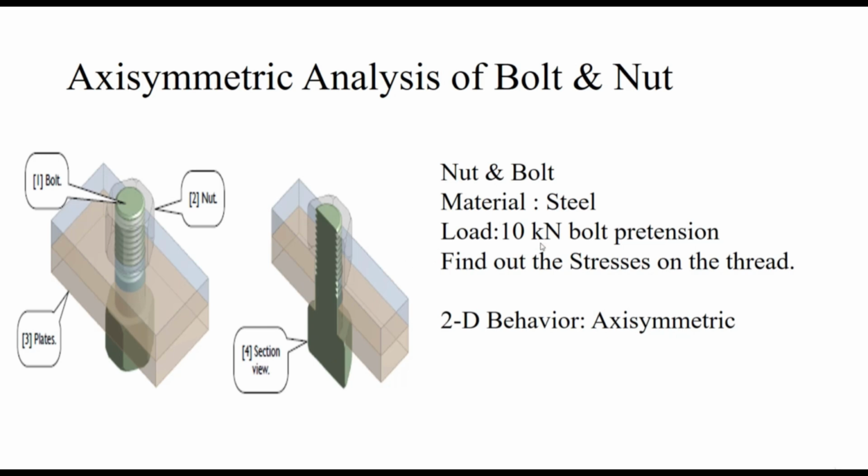Our aim is to find out the stresses that are developed inside the threads present on the bolt as well as the nut by performing analysis in ANSYS Workbench. We are going to use the axis symmetric nature present inside this geometry in order to simplify our analysis. Thank you.